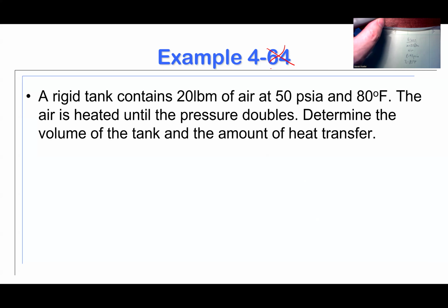We're going to heat this air up until the pressure doubles. P2 is equal to 2 times P1. We want to find the volume of the tank, and we want to find the amount of heat transfer. I'm going to call it heat in. Why do I call it heat in? Because we're going to heat it up until the pressure doubles. Now, there's something else given to us here that's not a number.